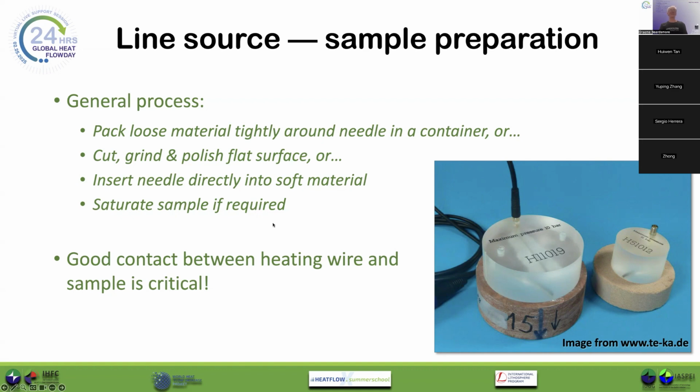And you may or may not need to saturate the sample. If you're looking at dry rock chips and you know that those rock chips normally sit in a fully saturated environment, you might want to make the measurement with those rock chips fully submerged and saturated in water. But it's critical to ensure good thermal contact between the heating wire and the sample.